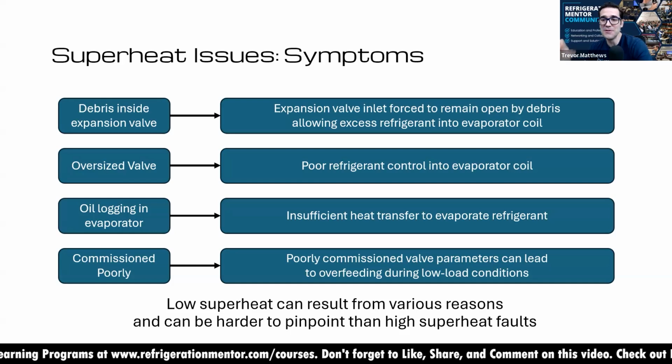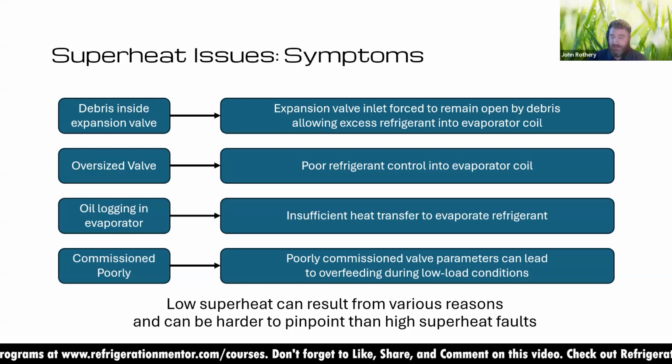Yeah, me too. What about you, John? What are your thoughts? Yeah, it's a great feature, and like you say, you can spot a step change when the valve's starting to become blocked, and it starts increasing the percentage opening, or say your suction probe falls off. It's still getting the temperature from the case, or it becomes slightly detached. Then you'll start to see the valve go 0, 100%, 0, 100%, where it's not seeing the superheat it wants to calculate. So yeah, it's good for diagnosis and pinning things down without a doubt.